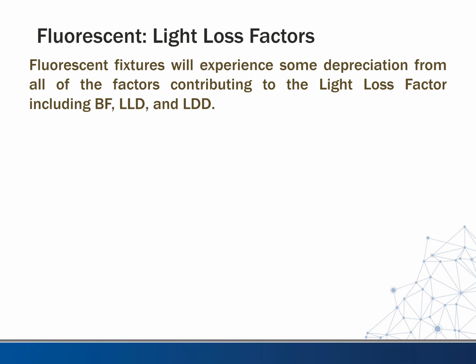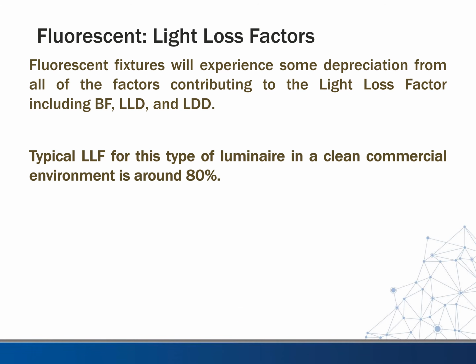Fluorescent fixtures will experience some depreciation from all the factors contributing to the light loss factor, including ballast factor, light dirt depreciation, and lamp lumen depreciation. The typical LLF for this type of luminaire in a clean commercial environment at least is around 80%.